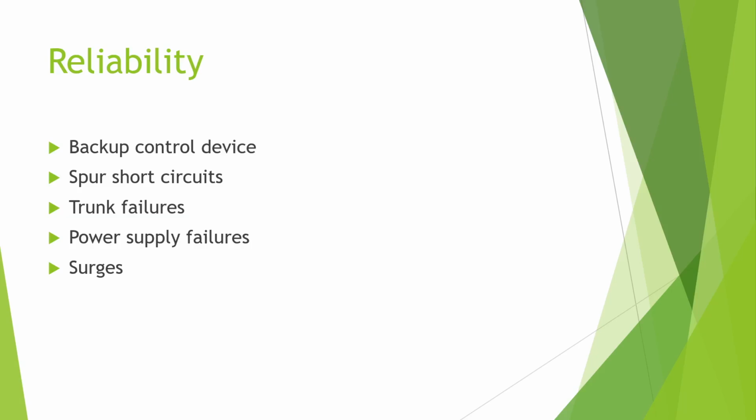Now, this obviously is not always going to be possible to have conduit running everywhere, because if you have something that's moving that has that trunk line that needs to get to it, you can't protect it with conduit. So that's where the armored electrical cabling comes in. So you could protect it with something like that. Still not the best thing in the world, in my opinion, to have this armored cable flexing constantly. But any wires that are flexing constantly is also just a failure point over time. If you take a wire and just bend it back and forth a whole bunch, you're stressing that same spot, it's going to fail. Now having a nice big loop, so you're not stressing at one specific point, you're stressing it over an entire arc, is going to be better, but still something we need to think about.